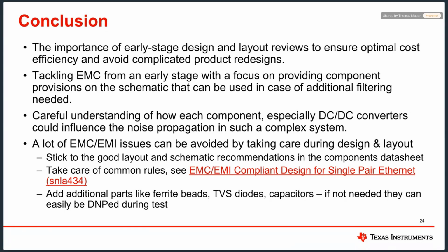system. So a lot of these EMC and EMI issues can be avoided by taking care during the design and layout. On one hand, you can stick to good layout and schematic recommendations, and many times the component data sheet, so the device data sheet, already shows good recommendations. So make sure that you read this in the layout recommendation part.